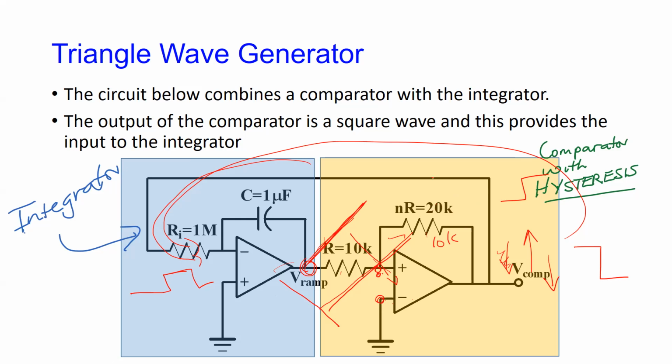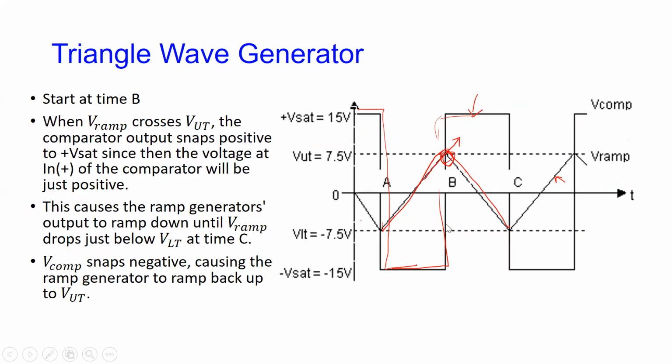All that is happening is that as this crosses that threshold, the threshold is really here, which doesn't quite make sense. That's why we have the two resistors in here. But if you understand, as soon as the voltage crosses whatever the upper threshold is, that signal is fed back to the integrator, and it integrates that and does this, right?